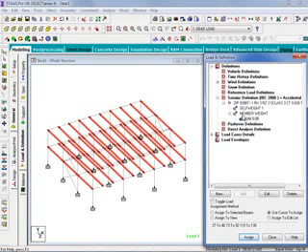Now these load items within our seismic definition are just going to be used as part of the seismic base shear calculation. They're not actually loading the model as a dead load or a live load. With this seismic load definition, the design base shear will be calculated based on equation 12.8.1 of ASCE 7-05 for IBC 2006. It will then be distributed to each floor, and a collection of nodes with the same Y-coordinate value is considered to be a level for the purpose of determining the vertical distribution of seismic load in accordance with Section 12.